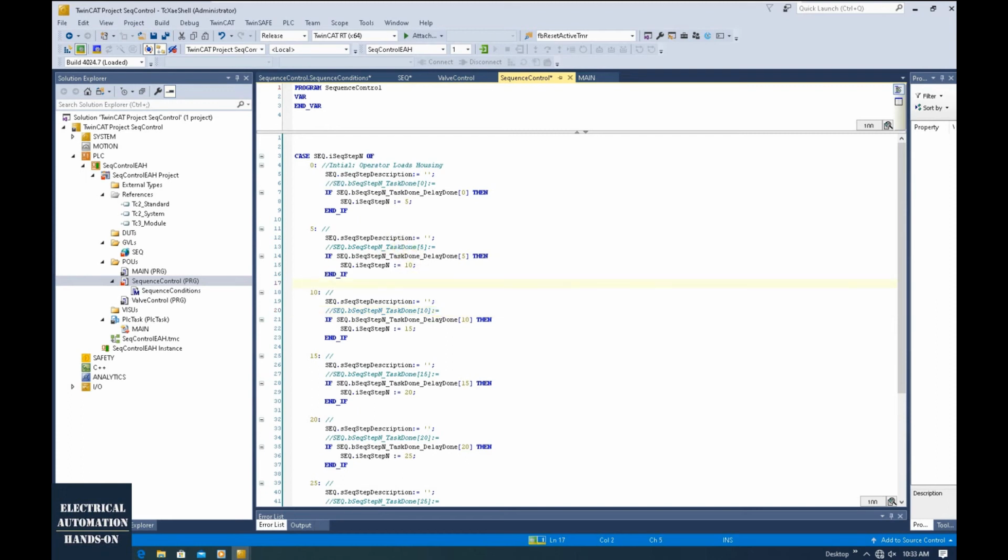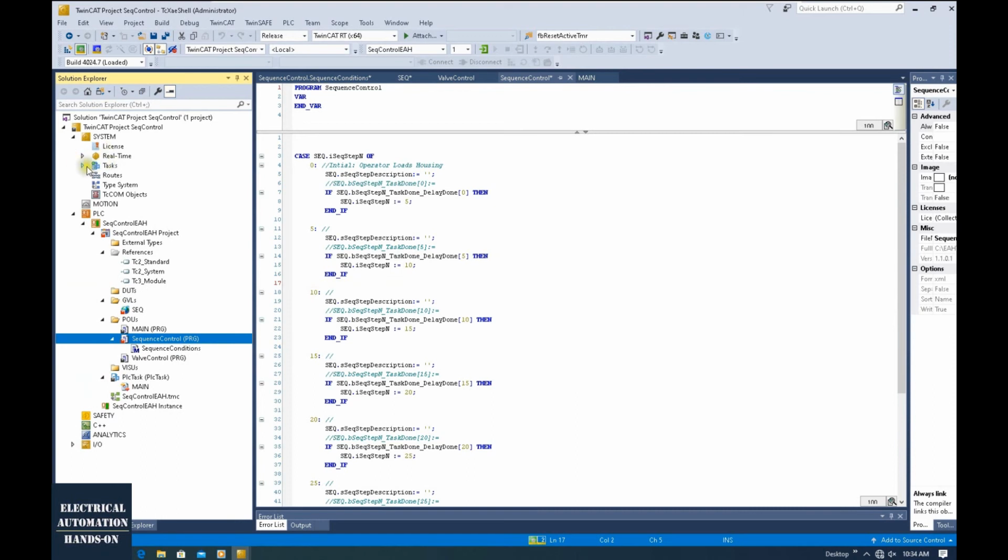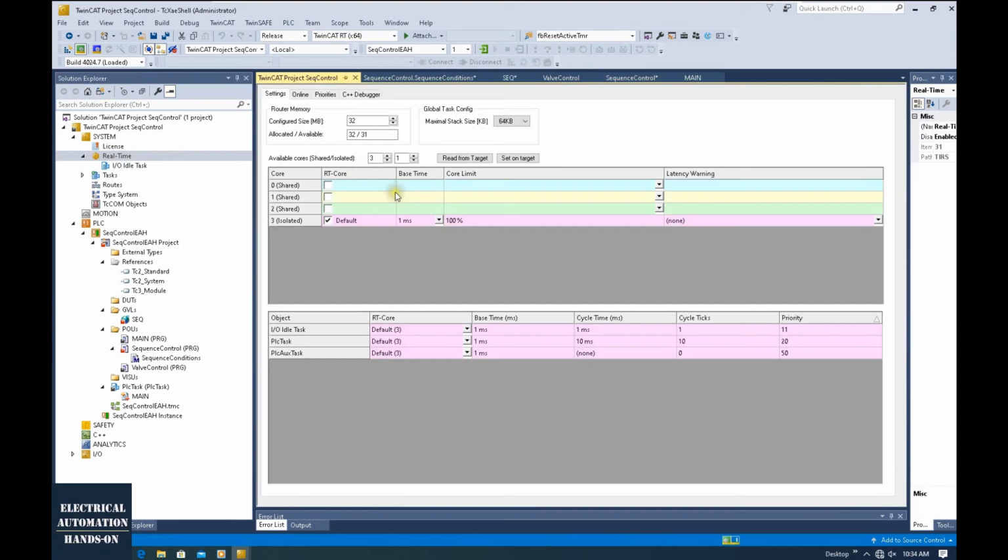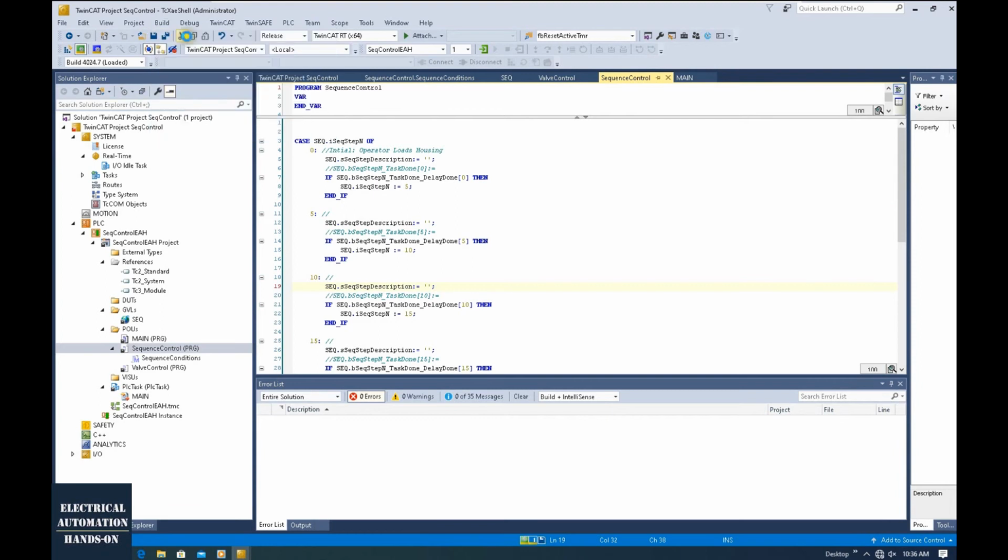Okay, I will download this program, and currently I'm using this TwinCAT3 within one virtual machine. To allow my laptop to run this TwinCAT3, basically run as a simulated controller, I need to use my virtual machine to run this program. And to allow my virtual machine to run this program, firstly we need to go to this real-time setting. Let me click this build solution.